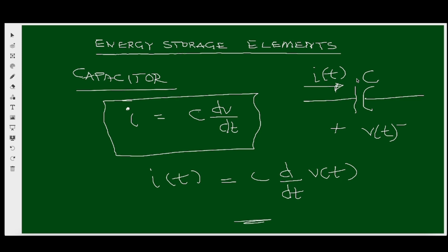Capacitors are constructed with two parallel conducting plates of a particular area separated by a distance d, and it has a capacitance C. If you want to get the capacitance of a capacitor in terms of internal properties, the capacitance equals epsilon A over d. Epsilon is a Greek letter, and it is a property of the dielectric of a capacitor, called the permittivity.